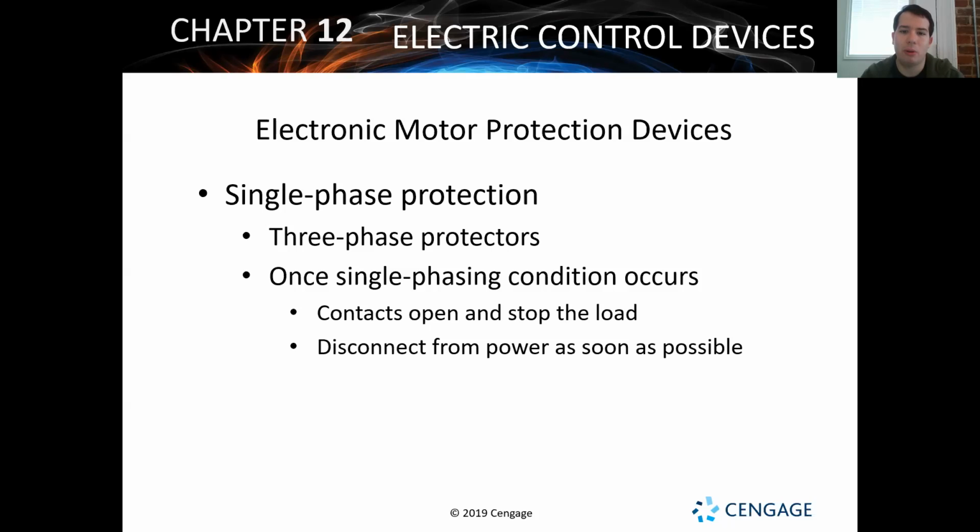So having something that's going to watch and make sure that it doesn't go from a three-phase system into a single phase system helps protect a lot of the different components, all of our motors and everything like that. So really we're just trying to stop the load, protect it, disconnect our power, so that we have the fastest way to control and protect our motor.